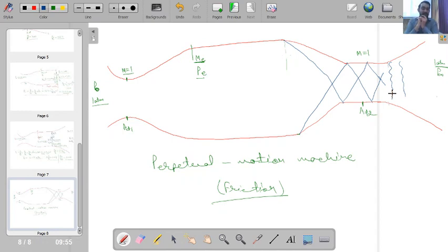Okay, so as it will be identical to a Mach wave, and earlier we are having a combination of oblique shock waves, the total pressure reduction in this combination of oblique and a weak normal shock wave will be less in comparison to the pressure reduction in a single normal shock wave. That we have proven earlier also in some of the numerical problems I discussed in the class. So this is the reason that generally for designing a wind tunnel we prefer this type of design.